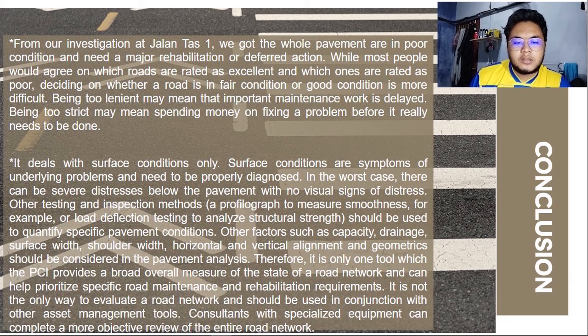Therefore, it is only one tool. The PCI provides a broad overall measure of the state of the road network and can help prioritize specific road maintenance and rehabilitation requirements. It is not the only way to evaluate a road network and should be used in conjunction with other asset management tools. Consultants with specialized equipment can complete a more objective review of the entire road network. Thank you.